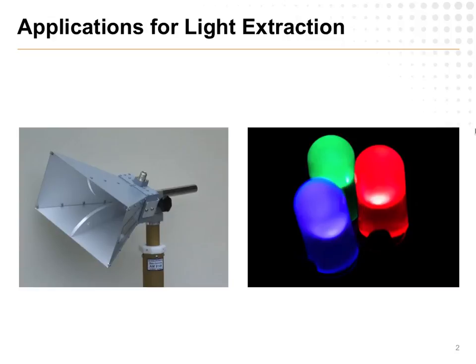So remember, when you make these at a semiconductor fab, you have a wafer that's maybe 6 inches or so, about the size of your hands in a little ring here. And you might process like 5 of these at a time, and that little batch would probably cost you somewhere around $50,000 to $100,000 to process. But how many chips do you think you can get out of 5 wafers that are about 6 inches in diameter, if the average chip size is 1/10 of a millimeter or so? If you just run the math order of magnitude in your head, how many die do you think would come out of that? 10,000, 100,000, a million?